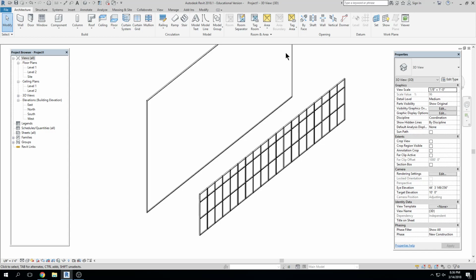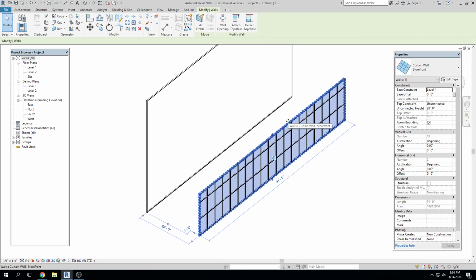Otherwise you're doing storefront and you're limited to like a 5 by 10 piece of glass so that it's reasonable. So we decided that using storefront was a good system because we can set the spacing of the mullions to keep within the parameter of how big our glazing needs to be before it gets expensive.